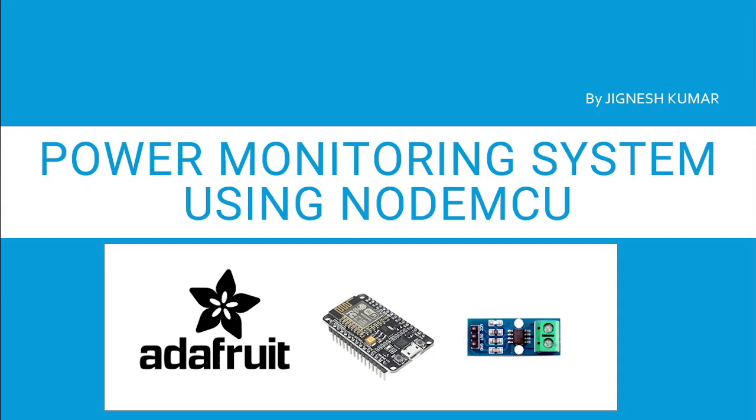Welcome everyone to a new IoT tutorial. In this tutorial we are creating a power monitoring system using NodeMCU. I am going to use the ESP8266 Wi-Fi module and this ACS712 current sensor module, and using these we are going to measure the current and power, and send this data to the Adafruit.io IoT platform. For that we are going to use the MQTT protocol for sending the data to the IoT platform. So let's get to the demo.